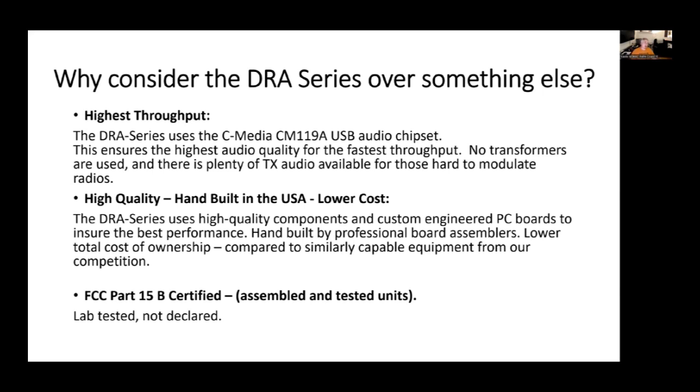Transformers can create a lot of problems, especially for any application that's using QAM. Quadrature amplitude modulation has two distinct points to it, and that is amplitude and phase. And unfortunately, a transformer can ruin both of those.